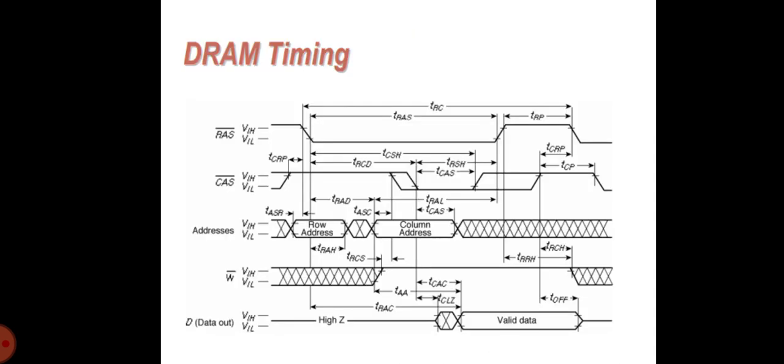Here you can see the simplified timing diagram of a 1/4 Mbit DRAM memory and some of the imposed timing constraints. The full specification involves more than 20 timing parameters, all of which have to be held within precise bounds to ensure proper operation. Obviously, generating the correct timing signals for these memories is a non-trivial task. All the internal timing signals such as EQ, PC, SE signals are derivatives of the external control signals. To maximize performance, some of those signals have to fall within very precise intervals.